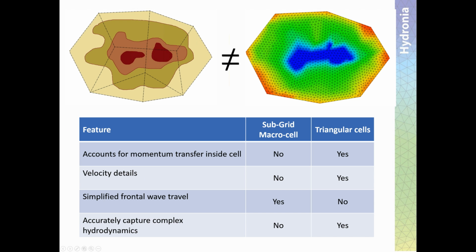And when you're trying to model rapid flows, you're not actually capturing how the velocity or the flow is behaving here. For rapid flows, the only way to go is to refine the mesh and resolve the full equations. Now, in some situations, very slow flooding situations, that may work, and it may actually be convenient, but you have to use it with care, because if you're running a project with rapid flows, you're not solving the same equations there. So you have to use it with care.